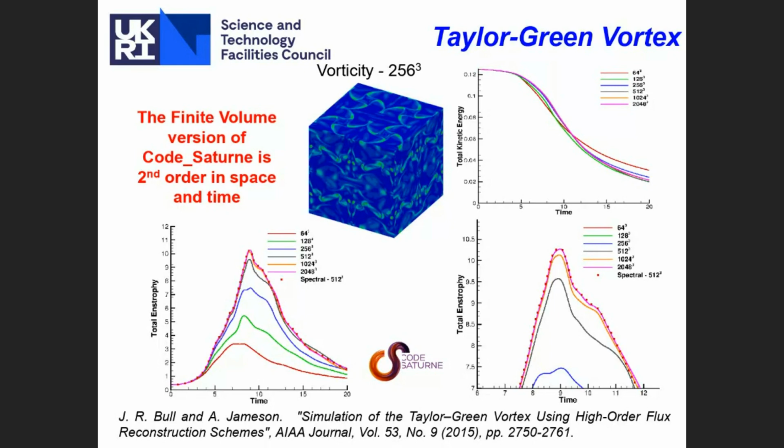But if you want to run simulations which are only with hexahedral cells and in a box, Code Saturne might not be the best software to use. You should use a DNS software with a much higher accuracy. Now, if you are going for more complex geometries, such as flow between tube bundles, Saturne is a good one, and it retains this second order accuracy in space and time.